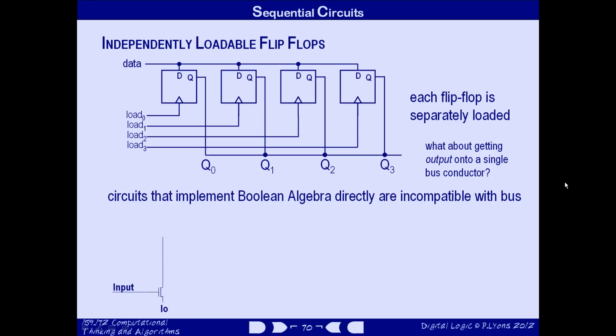until we connect an input wire to the vertical line on the left and make its voltage high. That is, when the input on the left is a high voltage, the transistor can conduct electricity from top to bottom. Then the wire at the top would be connected to ground, and its voltage would be, as we say, pulled low. So if that wire was used as the output of the circuit, we've got a way of giving it a low voltage, by connecting the input to a high voltage. Now that sounds a bit like an inverter, a circuit that implements a Boolean NOT operator, and in fact that's just what we've started to build.